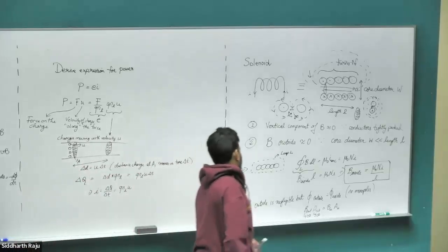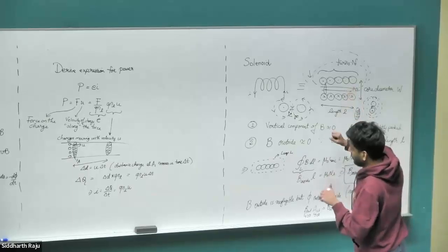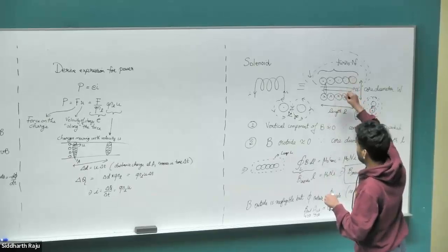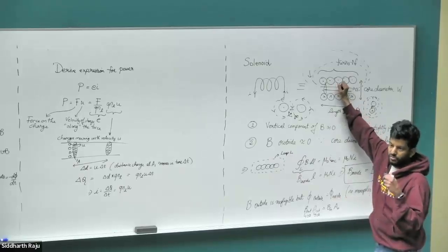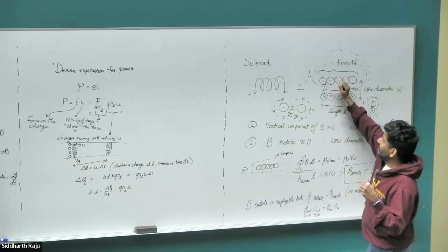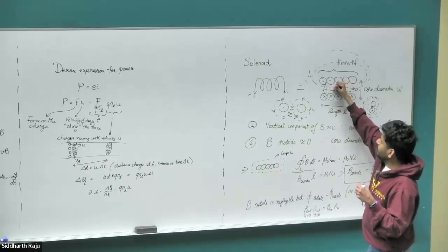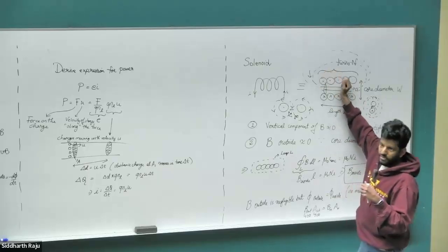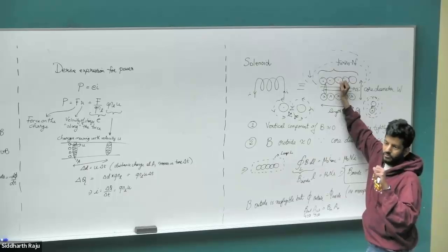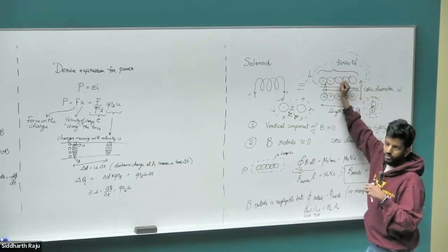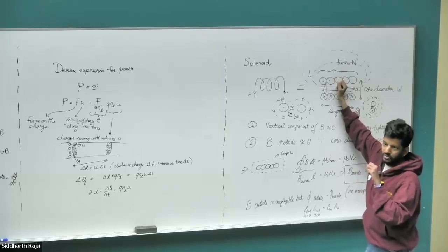No, it won't. The way you would improve this B field is not by changing what's on the outside, but by putting some kind of material inside, like iron, which makes the B field stronger. Once you have iron inside, there is not only going to be a B field inside, but there are going to be leakage B fields on the outside as well. But the iron has a much better pathway for magnetic field lines to pass through compared to the outside air. So most of the field lines would now concentrate in the iron core.